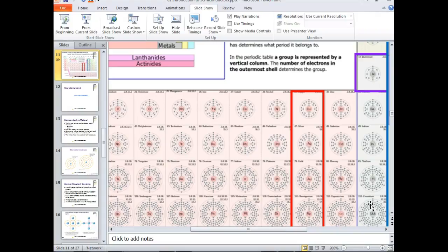So that means a wire that had a 0 gauge would be pretty big. A 24 gauge would be real small. So that's a gauge number. We can go to the next lower gauge number and use aluminum instead of copper. That's the rule of thumb. It would have approximately the same resistance over the same length.